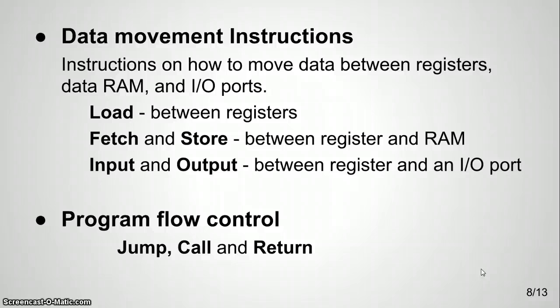The call function works in the same way as a jump instruction. In addition, however, it also saves the current value of the program counter on top of the stack, so that a return instruction may be used to bring it back to this point.